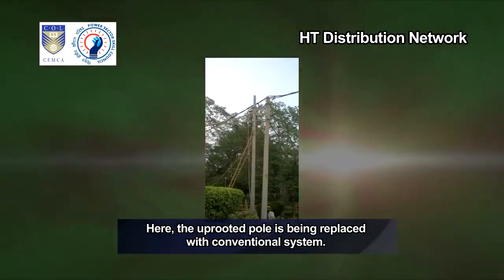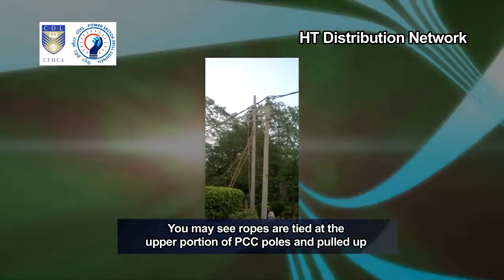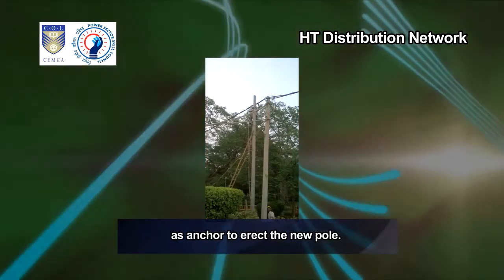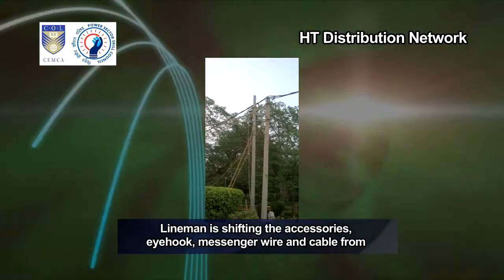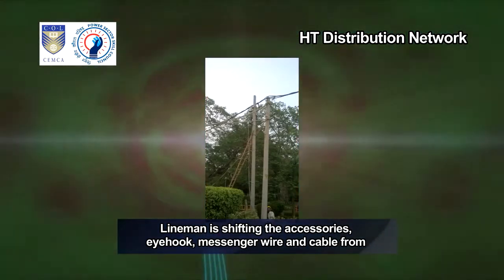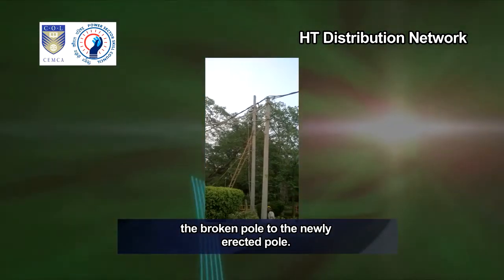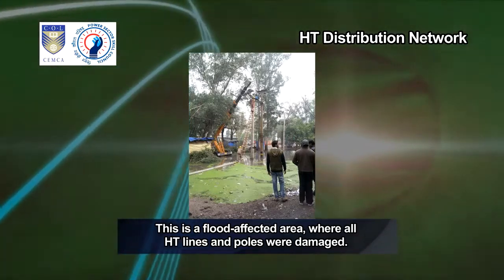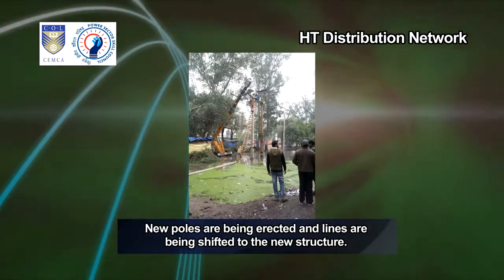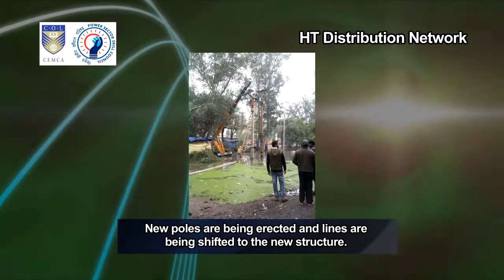Here, the uprooted pole is being replaced with a conventional system. You may see ropes are tied at the upper portion of the PCC poles and pulled up as anchor to erect the new pole. The lineman is shifting the accessories, eye hook, messenger wire and cable from the broken pole to the newly erected pole. This is a flood-affected area where all HT lines and poles were damaged. New poles are being erected and lines are being shifted to the new structure.